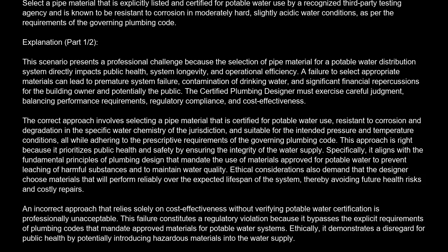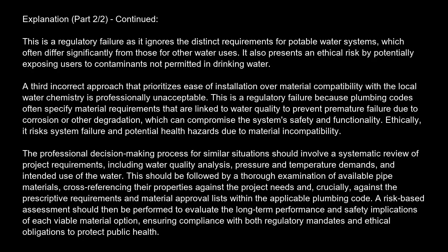Another incorrect approach that selects a material based on historical use in non-potable applications, without confirming its suitability and certification for potable water, is also professionally unacceptable. This is a regulatory failure, as it ignores the distinct requirements for potable water systems, which often differ significantly from those for other water uses. It also presents an ethical risk by potentially exposing users to contaminants not permitted in drinking water.